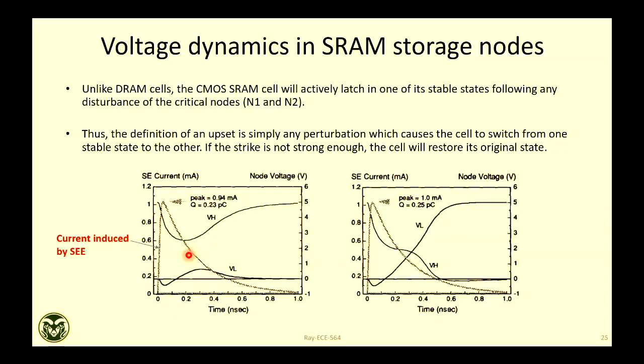But for DRAM, I think there is no one to rescue. So refresh, yes, you can increase the refresh interval, but typically it is carefully designed. The refresh interval is also power hungry, right? You have to refresh, which means your power dissipation goes up. So you should see more soft errors for DRAM for the same size. Questions?